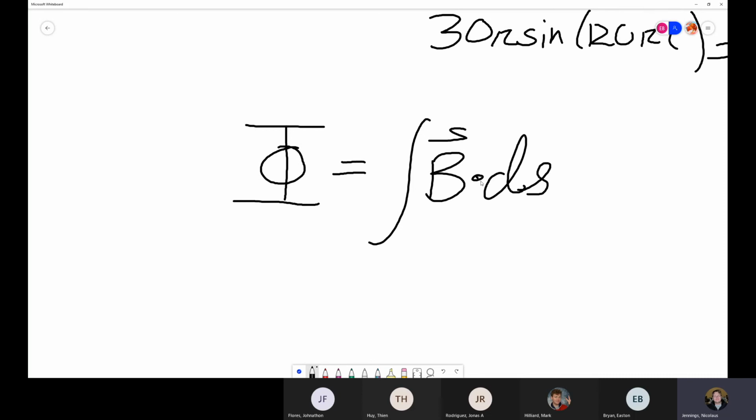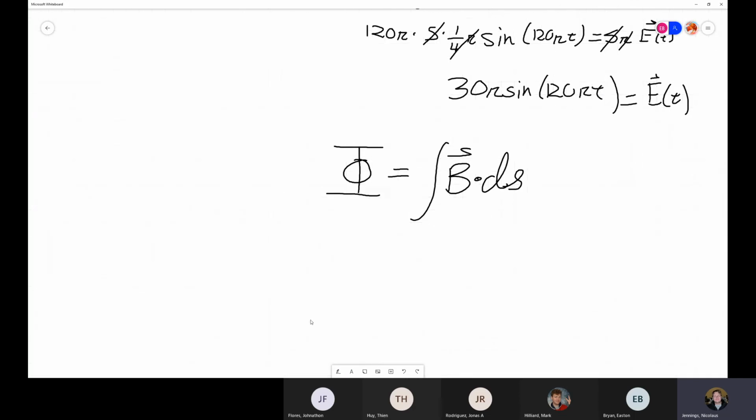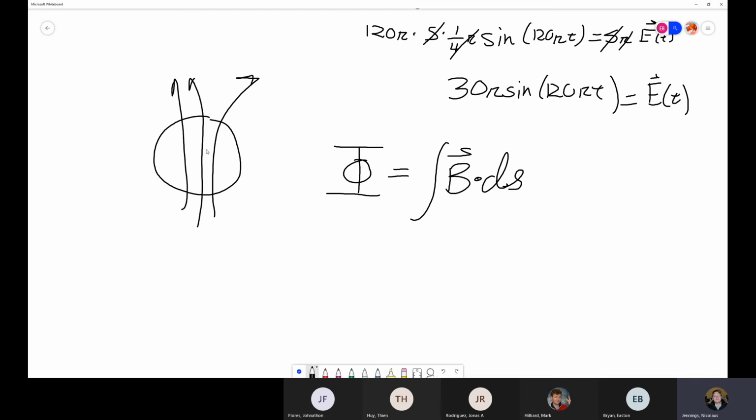So we're trying to figure out, and I'll preface this, you might think, okay, what's happening inside the loop? So you think, okay, there's H coming here, there are some B here, some B here, some B here. What we do is we assume that at the very center of the coil, all the magnetic field is concentrated, right? So we're trying to figure out what the maximum B is, and that's what allows us to determine the self-inductance. Yeah, there's some other stuff trailing out here, but as it gets closer and closer to the edge, it's really, really small. So we're really concerned just about the center.